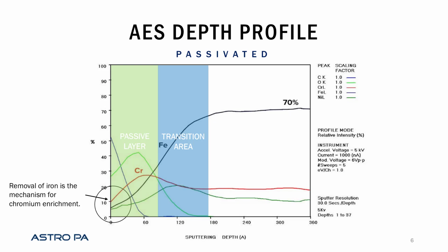And then third, I'll do a little overlay from the sketch on the 2 slides ago. We get some increase in the thickness here, but we're still within that 2 to 10 nanometer window. So this is about 80 angstroms. That's 8 nanometers. And then just to drive it home, the transition area where we got the nickel dark green line enrichment right there. And then once we're at, what is this, 180 angstroms, 18 nanometers, this is our metallic phase, exactly how it shows up in the material test report. So it's these 18 nanometers that are providing us the majority of our corrosion resistance.